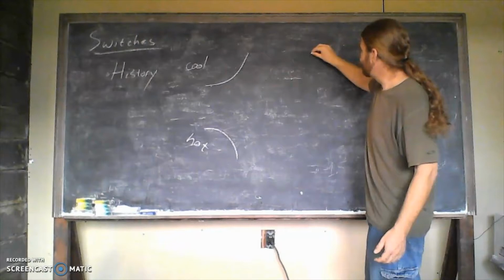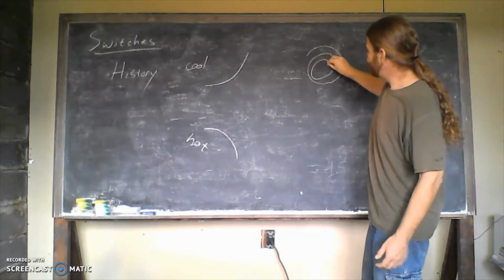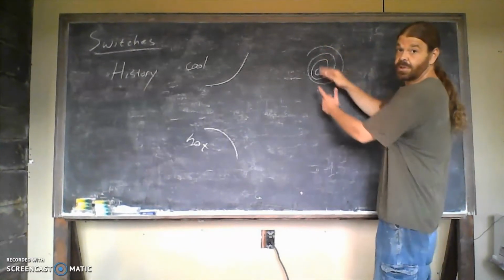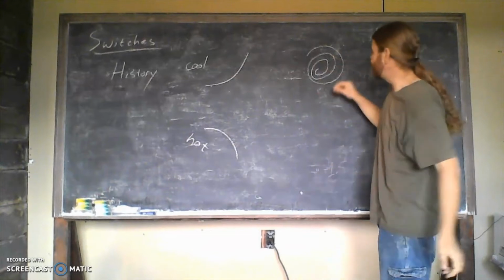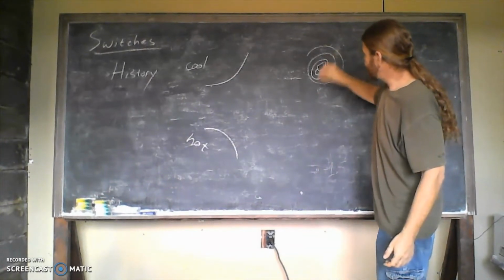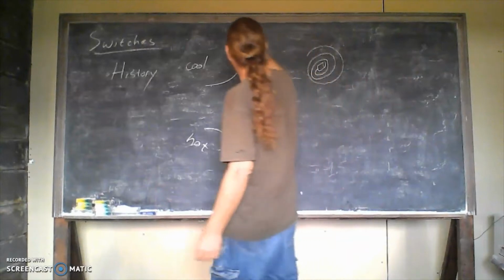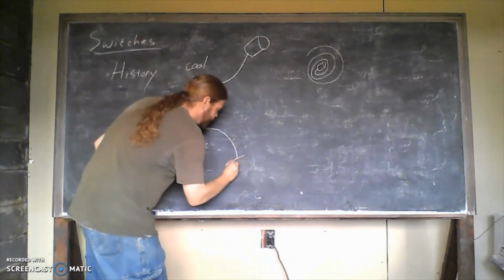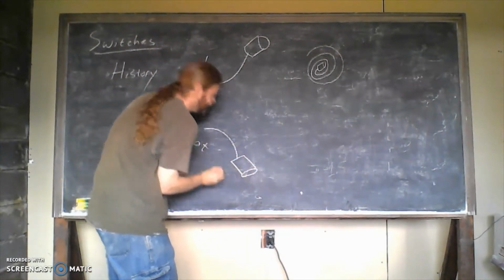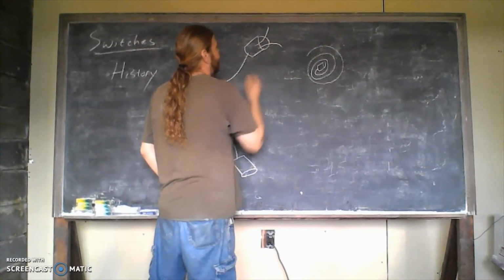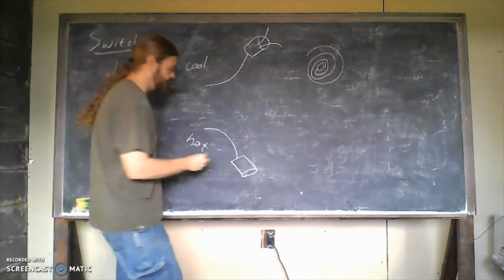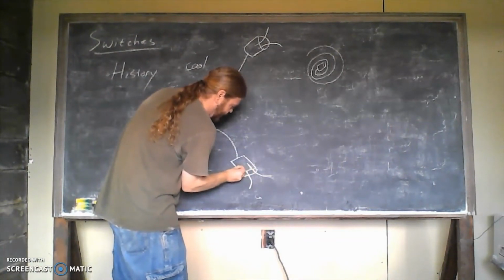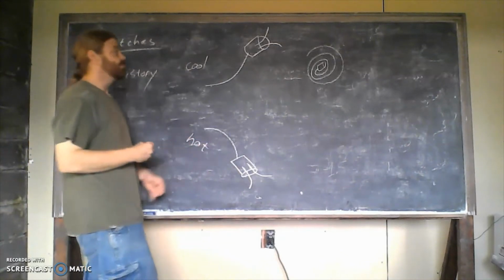I simplified the picture here. We typically do a coil of them, and that way it would only move just a little bit. That coil is going to go back and forth. And at the end of that, there'd be a little glass tube, and that glass tube would be our switch, what actually controlled the switch. Coming out of our glass tube, we have wires to tie into a circuit. They run into the tube a little, but are not connected to each other. They're separate from each other.